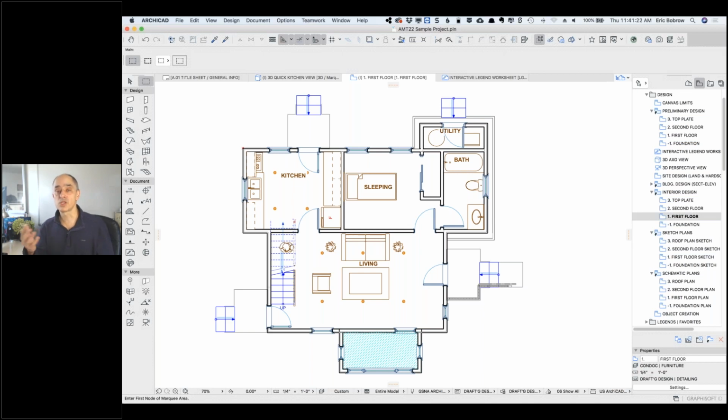You'll need to synchronize the layers because the layer system is different in MasterTemplate, but that's pretty easy. Let's just say that you have 25 layers that you've used so far. Could be 15, could be more, but whatever they are, you just go and say, the layer called A walls here, in MasterTemplate, it's called A walls exterior, or just different naming. And you literally say, I'm going to delete this layer and move everything onto the next layer.